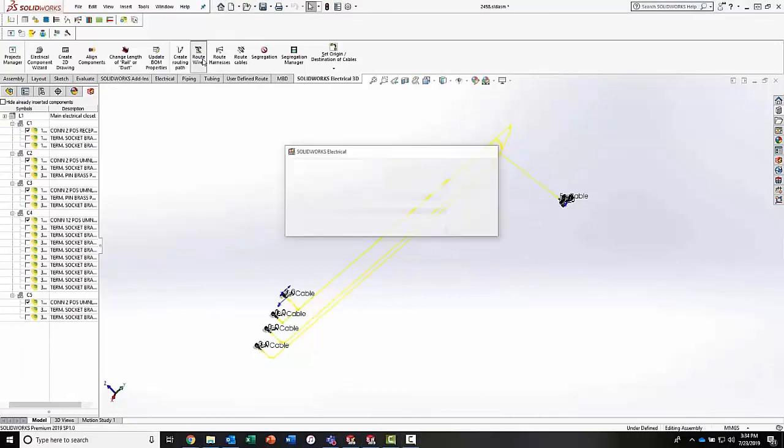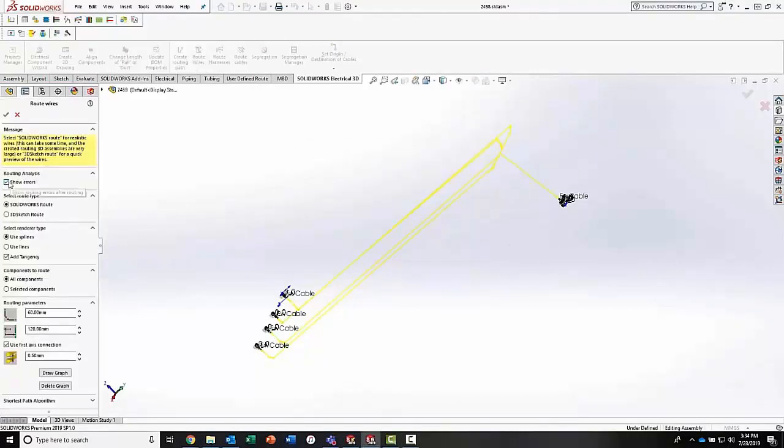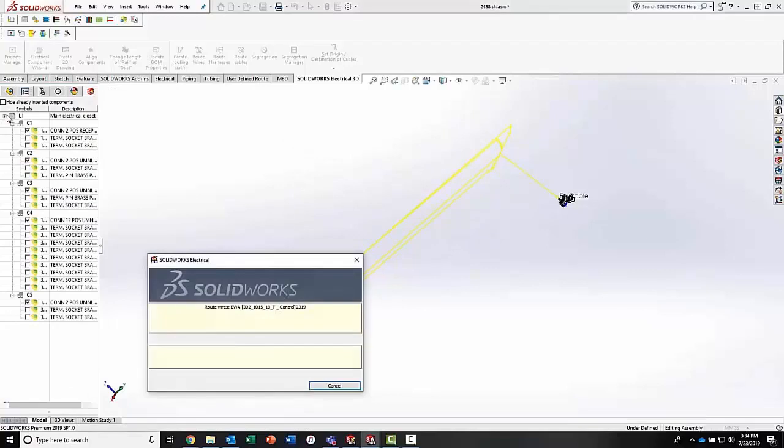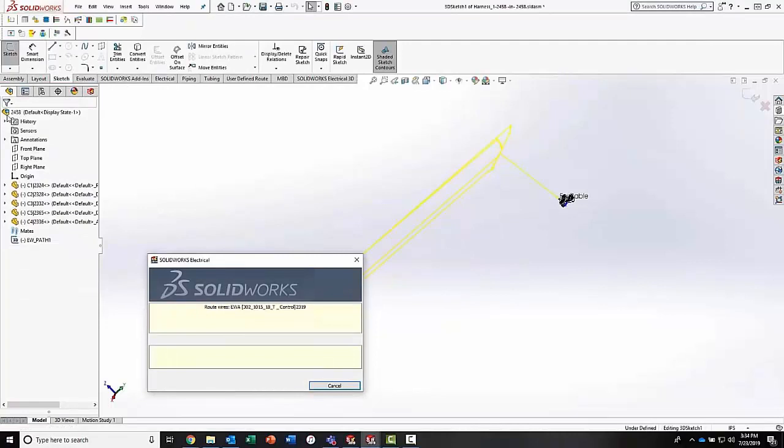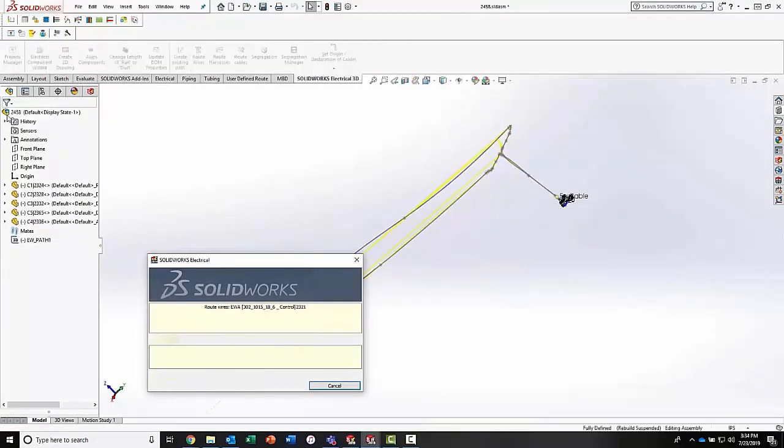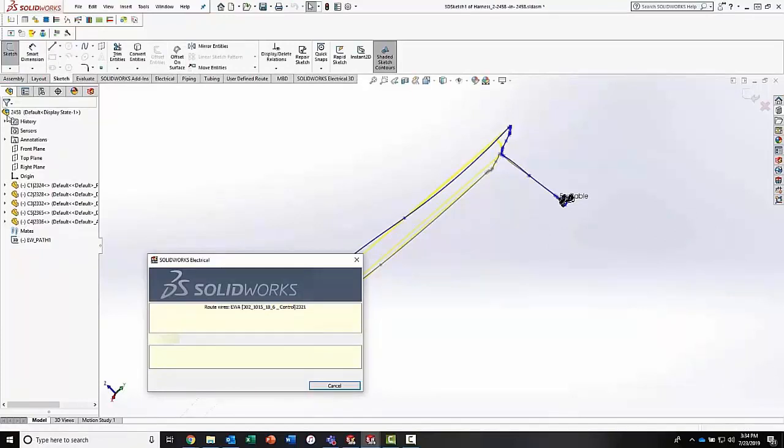I am now going to try and route two different ways. One is with routing of wires. So in your schematic, if you've drawn everything, the first thing you want to do is go ahead in your routing parameters and set up to route wires. However, you can also route a secondary way. The secondary way is through a harness, which I will show you in one moment.